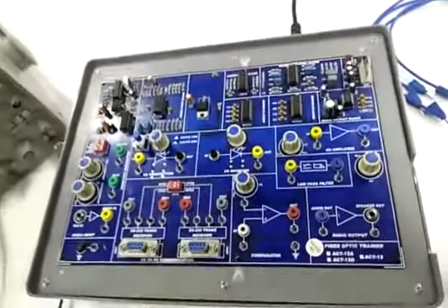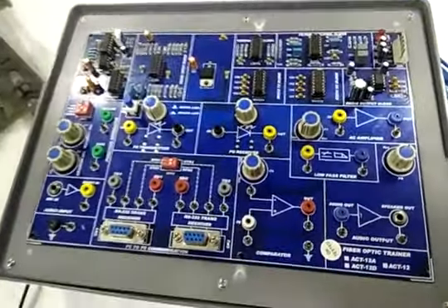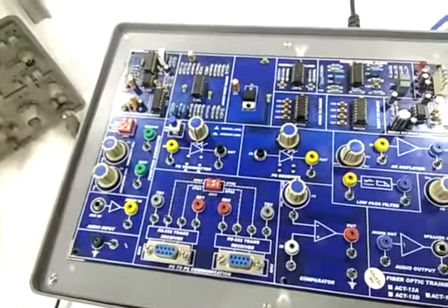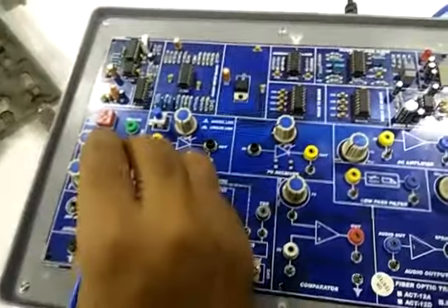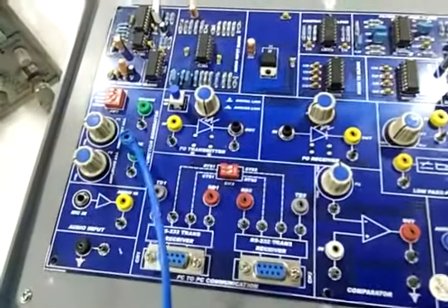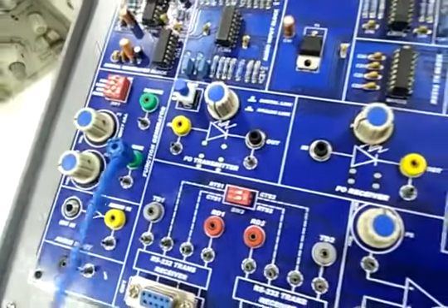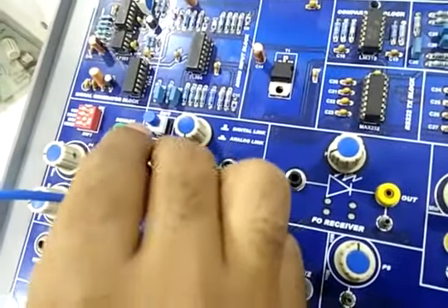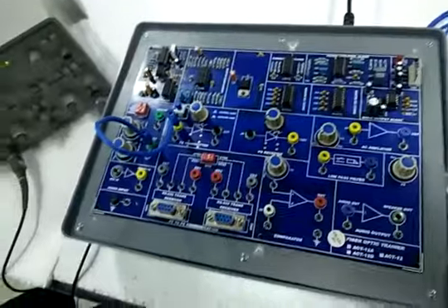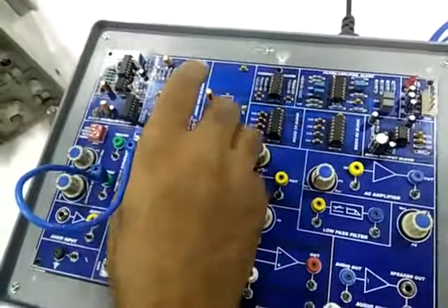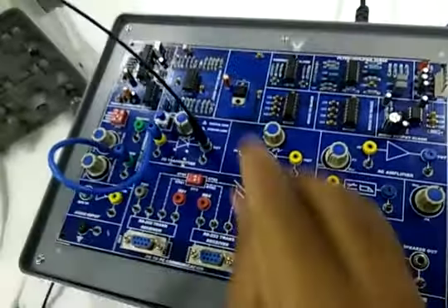Now we will see the experiments related to analog link on fiber optic trainer. The experiment is setting up a fiber optic analog link. Make the connection as given in the manual. For that, connect output of sine to input of FO transmitter. Connect 1 meter fiber cable between FO transmitter and FO receiver